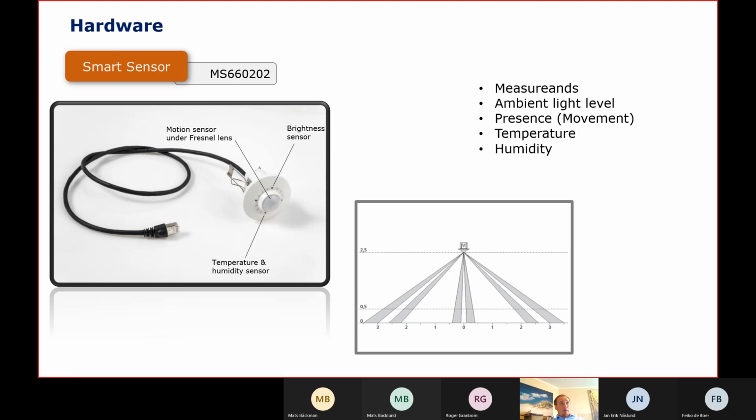So what I said earlier and introduced was a PoE solution. All of those devices are individually connected to a PoE switch, and on our switches the automation layer is connected, so we can create very granular solutions. We count the LEDs inside the project and the needed sensors, and then calculate how many PoE ports we need, to put those in a more cost-efficient way.